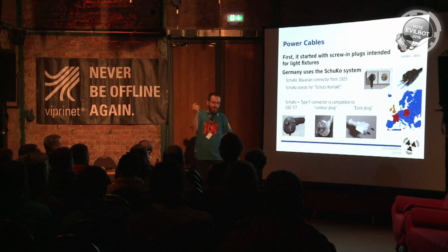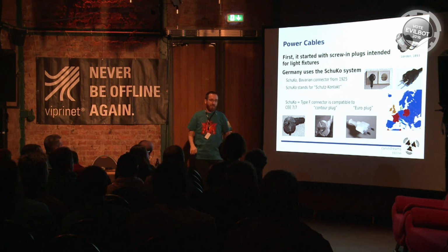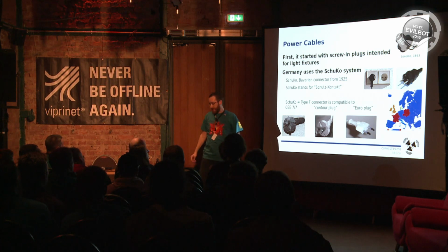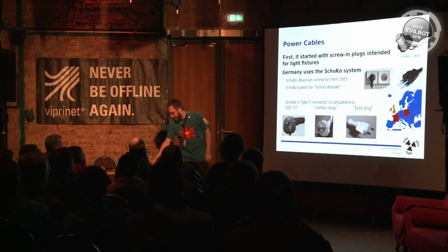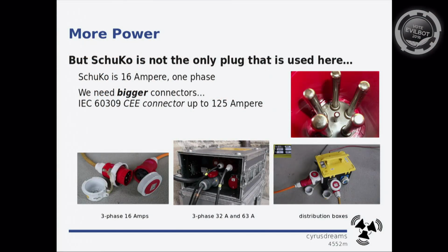So our lamp fixtures in all the blue countries are designed in a way that the plastic is reaching far high on the bulb so that this doesn't happen. But if you bring your own stuff from outside to the blue countries, just make sure that neutral and phase might be somewhere else. But we need more power at the revision. Such a Schuko connector can just deliver 16 amps and one phase. So we have to step up a little bit.